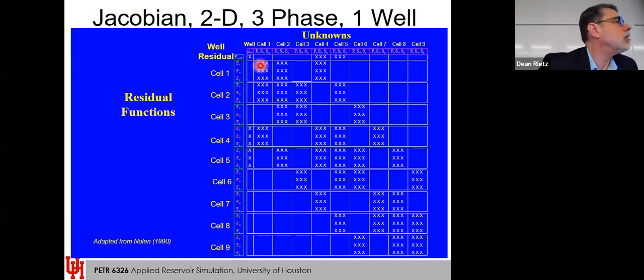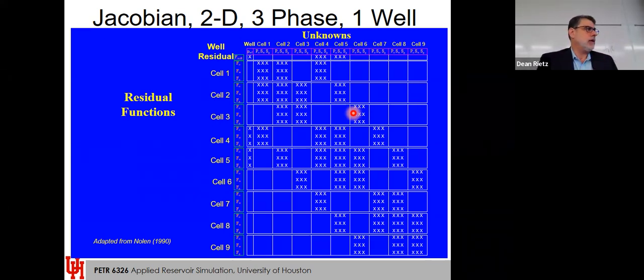After completing Darcy's law, then we go into this Jacobian. Yeah, well, these are the same equations. The Jacobian is the matrix, and it's the process of inverting the matrix to solve for the residuals. And if they're small enough, the matrix inversion is another iteration in itself. And once that's done, that's where you get into matrix solving, because it's an iterative process. They're non-linear, so you have to iterate on the Jacobian. And then once you get the Jacobian, you go to solve for the saturation. And then if the error is small enough, you move on.